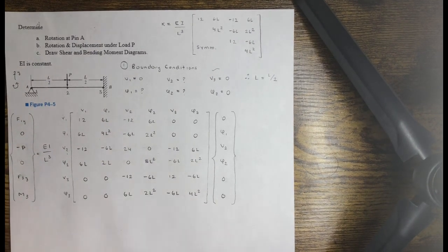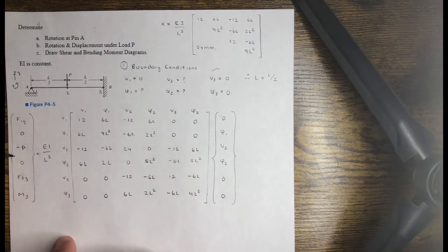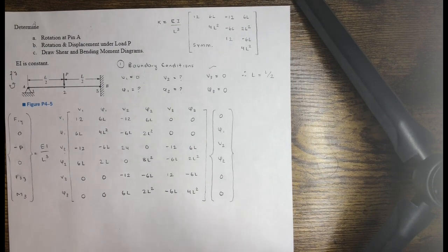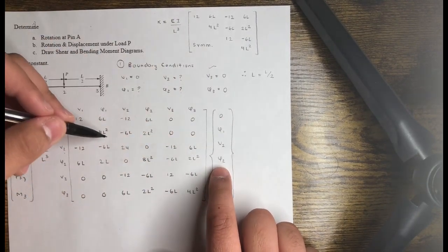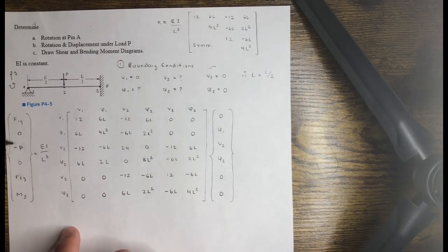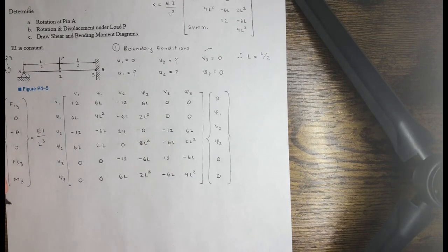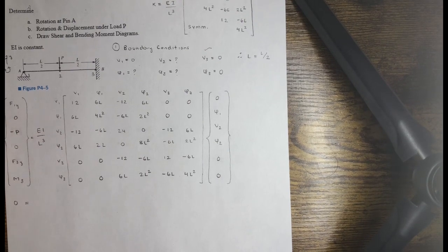So cool, we applied 6 conditions: 3 boundary conditions and 3 loads. So now we can go ahead and start assembling the equation. We always focus on the ones we don't know. In this case, these 3 equations right here, phi1, v2, and phi2, where you know your forces and moments. So the first one is 0 equal to EI over L cubed, but I'm going to divide EI over L cubed to this side. When you divide 0 by this, you get 0, so this goes away.